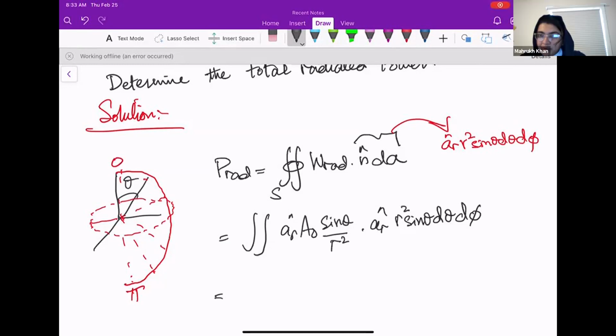Okay, and if you noticed last time, when we did angles in the far field, we were also putting 0 to pi for theta and 0 to 2 pi for phi. So you will notice that the far field sphere will complete if you use 0 to pi and 0 to 2 pi.